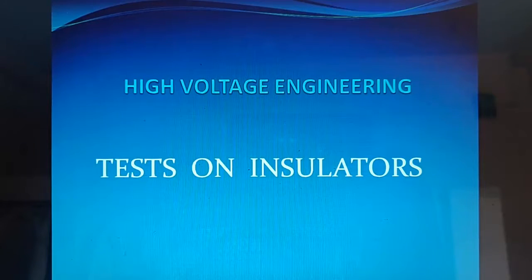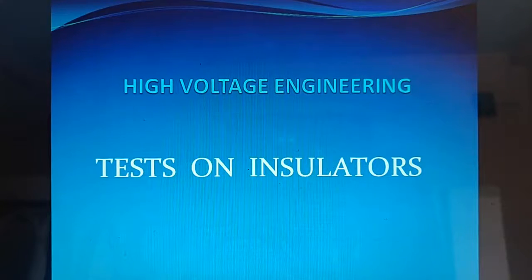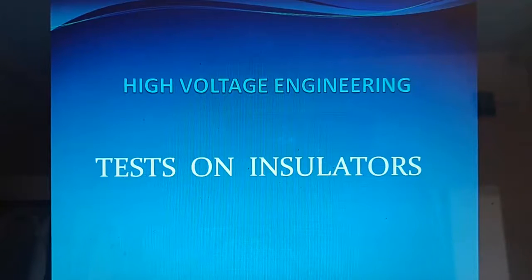If manufactured at a low temperature, it will become porous. And due to this, it will absorb moisture from the air and the insulation will decrease. Due to this, leakage current will start to flow through the insulator, which will lead to insulator failure.